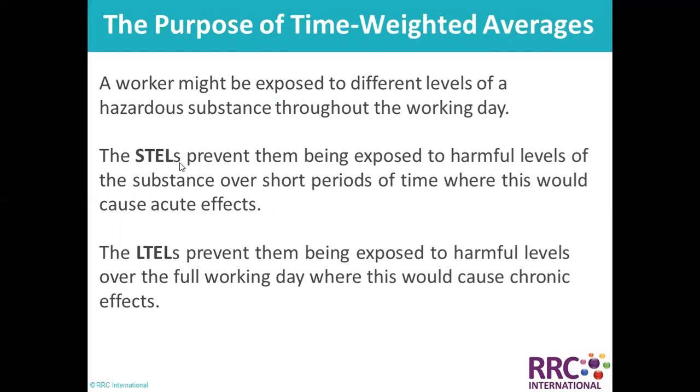STEL, that means short-term exposure limit, and long-term exposure limit, LTEL. STEL prevents them being exposed to harmful levels of substance over a short period of time, where this would cause acute effects. The LTEL, the long-term exposure limit, prevents them being exposed to harmful levels over the full working day, where this could cause chronic effects. So we can't allow people to work continuously in a toxic environment.